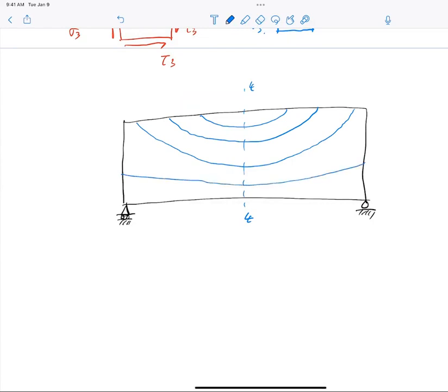You say, oh, Bob, I understand, all you're trying to do is draw me my tensile stress distribution in the beam. Yeah, but you see, where are these lines at? As I progress from top to bottom, my stress level increases. If these are my pattern of tension, we call it the pattern of principal stress trajectory. What we're seeing here is how concrete will respond, and how concrete will crack.